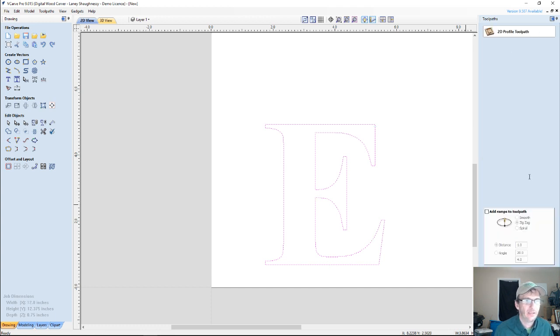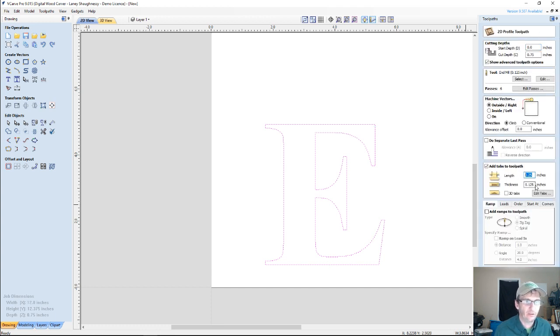So with tabs, you set the width of your tabs, your length, and your height, the thickness of them, and you can go ahead and cut. Now these will create a square type tab, however thick you want. If you choose the option of a 3D tab, on the outer edges it's much thinner, and then in the center of the tab it's 1/8 of an inch. If I have 1/8 of an inch thickness, then my tabs kind of cone up and down, so it's a little bit thinner tab. It's only 1/8 inch thick towards the center. That's what a 3D tab is.